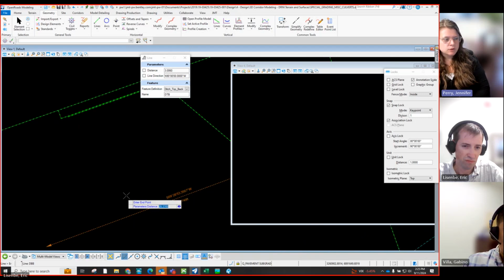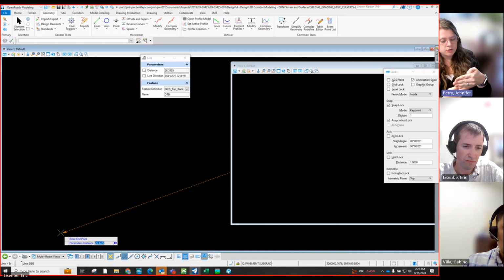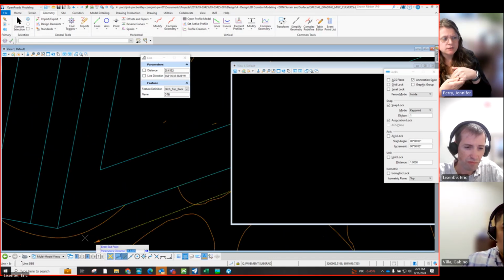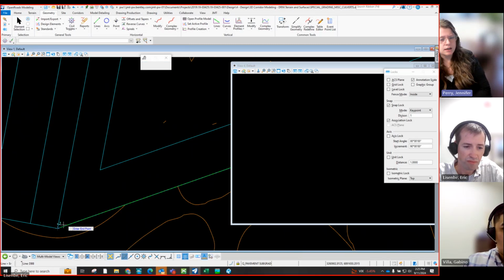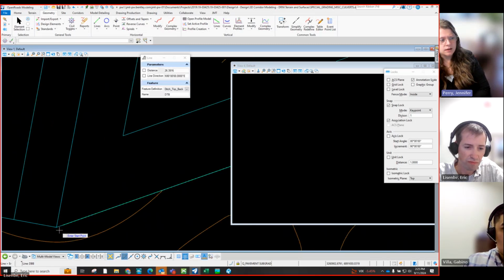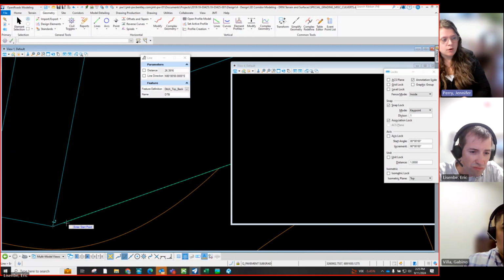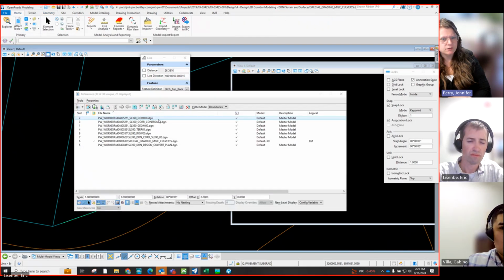The terrain model isn't able to recognize that. So for vertical elements, you've got to put a little bit of an offset so that the terrain doesn't blow up. And that's even when you start modeling retaining walls, you'll have to do that same thing. You'll have to put just a slight slope, if you will, to your retaining wall, even though it's vertical, so that if you're creating a proposed terrain, it's able to recognize that and not get all confused.